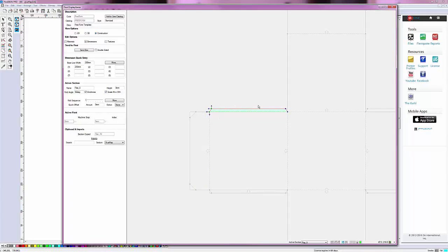So if I select points by using left click and drag, and also with shift and click options, I can select any set of points and change their stretch options. Okay, so changing these ones to proportional. Proportional. It's quite a laborious process.